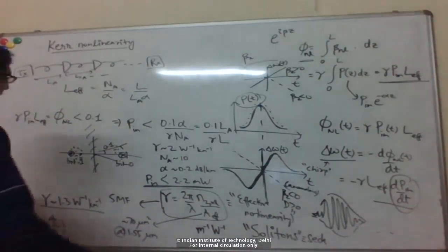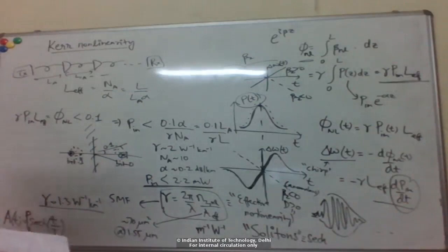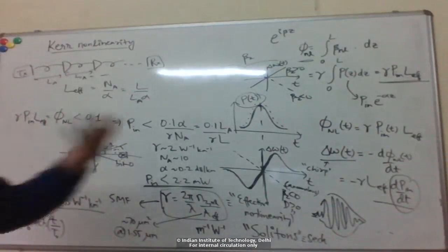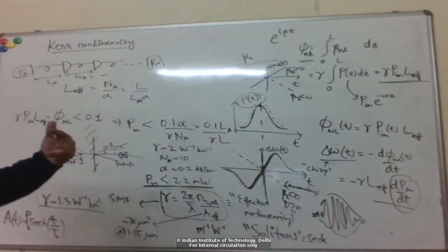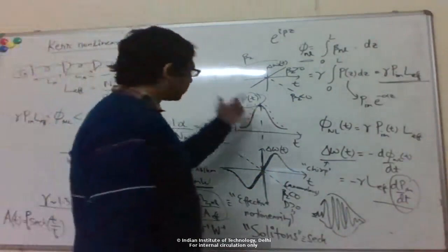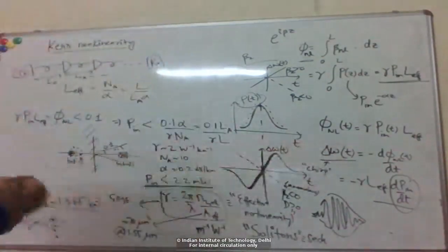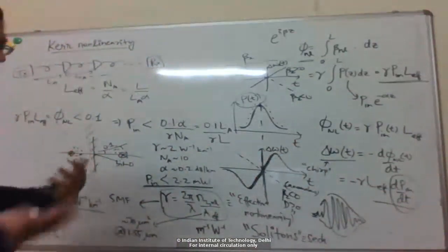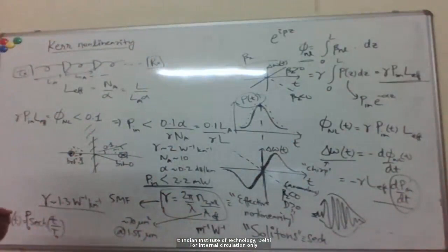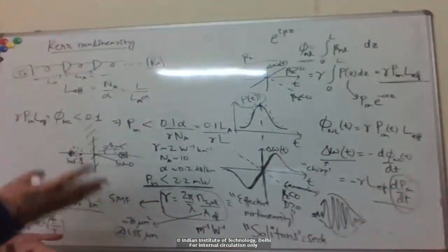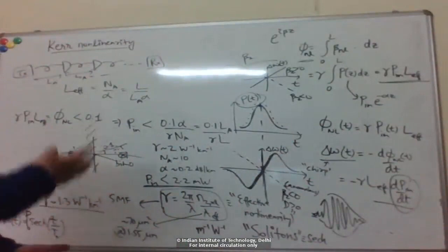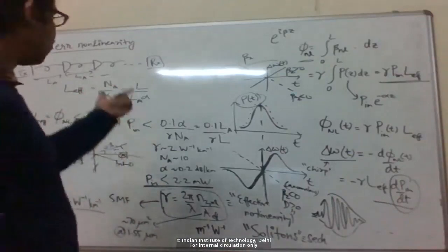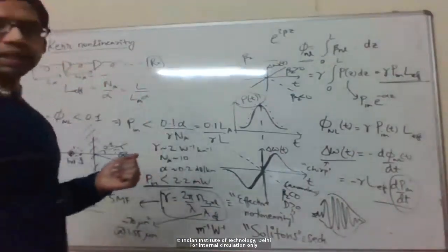Okay, and then basically a related effect for the self-phase modulation. The self-phase modulation again will be important for each wavelength channel, right? This is the phase induced by the pulse on itself, so it's basically each channel distorting itself. But there's a related effect if you have multiple channels traveling through the same fiber. One wavelength can also impose a phase shift on a different wavelength, due to the same mechanism. So we saw the refractive index was dependent on intensity.